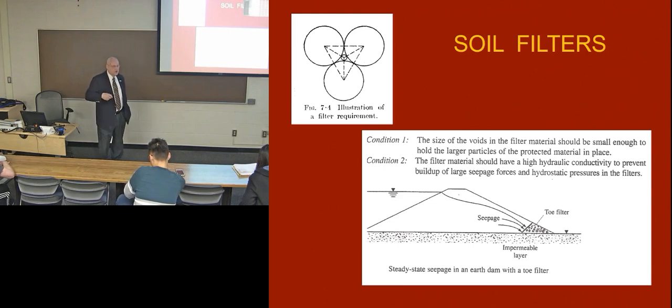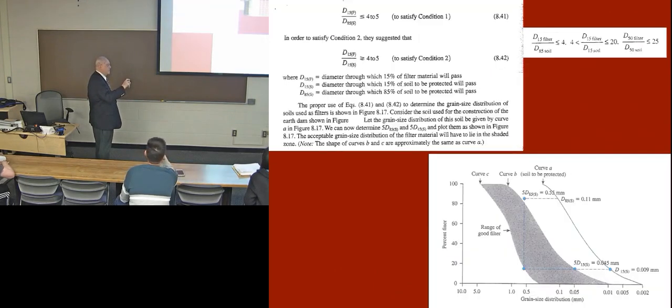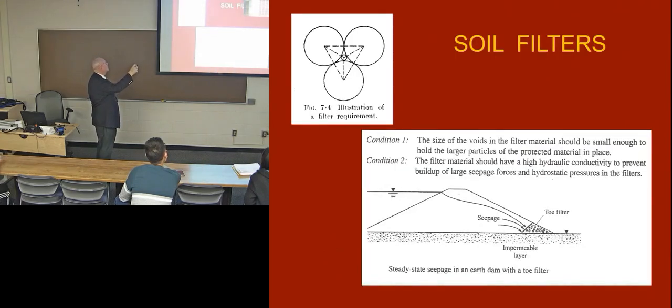That is internal erosion, wearing away of the soil. The filter is designed basically on the basis of this concept, that large particles can trap within their closed space smaller particles. And the ratio between these particle sizes is about 7 to 1, about, not exactly.